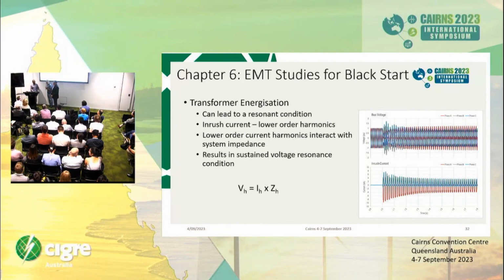I would say, maybe aggregate them and at least have their trip settings modeled correctly, because operators do rely on loads as stabilizing load for load generation balance and voltage control, and if they trip, they lose load effectively. So load changes, and they cannot control properly. So I think that's at least one of the most important settings you should capture.